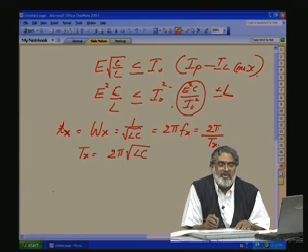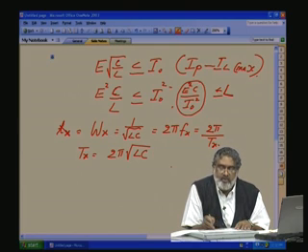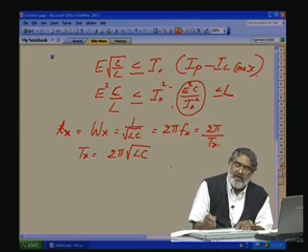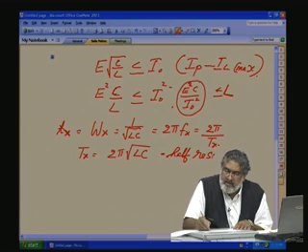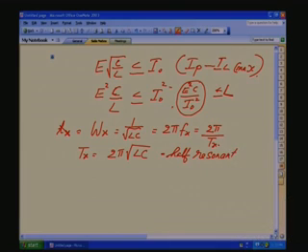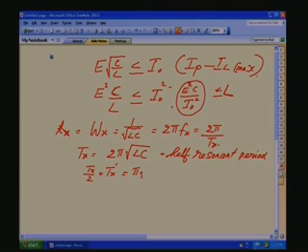But what we are talking about is the half resonant period, because of the diode we are not allowing the current to flow in the negative direction. So, the half resonant period, TR by 2, we will mark as TR dash, is equal to pi root LC.